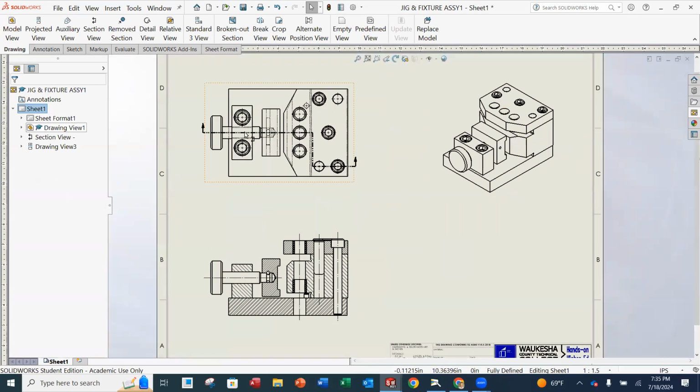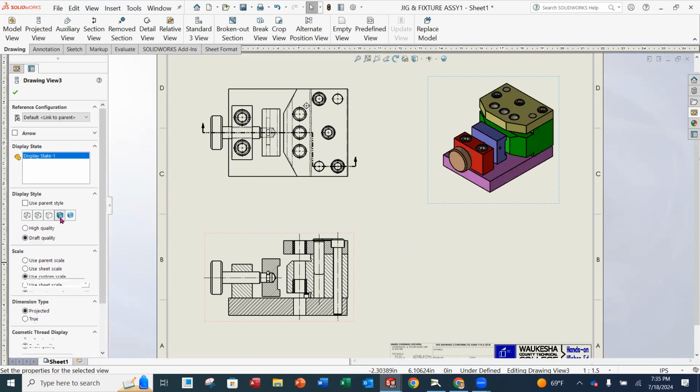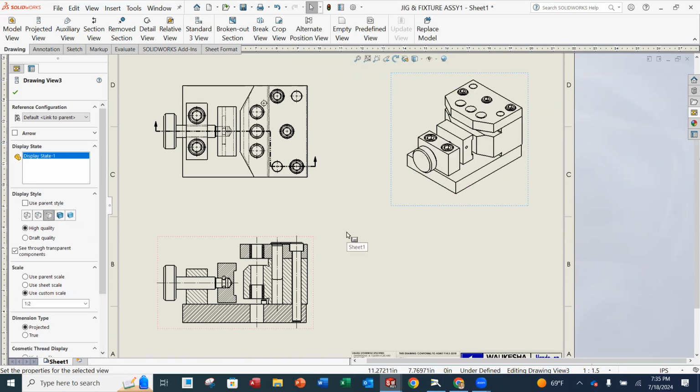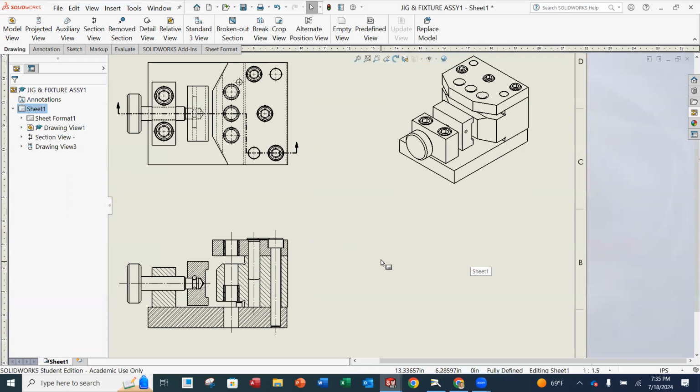Now here too, use your best discretion. If you look here, I'm going to click back on there. The one that I have it set at is hidden line removed. If you go over to the shaded with edges, if you like that, you can do that as well. I usually do that for individual parts, but for assemblies, I tend to not have all that shading because it's going to kind of be a darker blob. You won't be able to see the edges anyway. So I tend to use this one for assemblies, but you can use either one, whatever you feel you like.